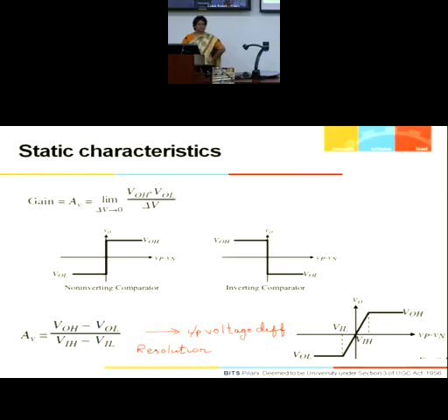Okay? So similarly with the change at VIH. It takes some time, so it is only at this point that it attains its full value, the logic one. This difference I will call my V input high, that is, an input for which the output will go high. And I will call this my VIL, for which the output will go low.